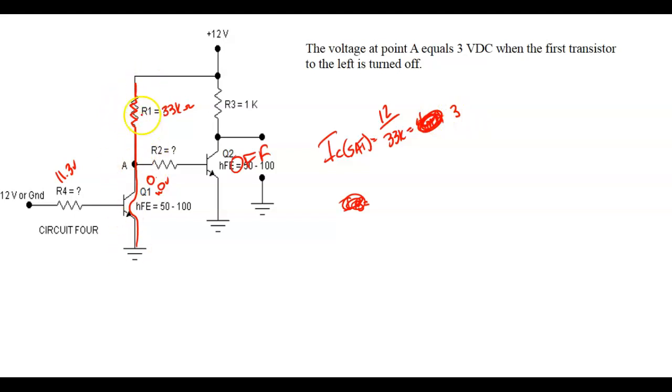We're away from this circuit over here, and what we've done is when Q1 turns off, R1 has to drop 9 volts. When Q1 turns on, R1 has got to drop 12 volts. So we have two paths. When this guy here is turned on, that's going to put our base voltage at around 0 volts.